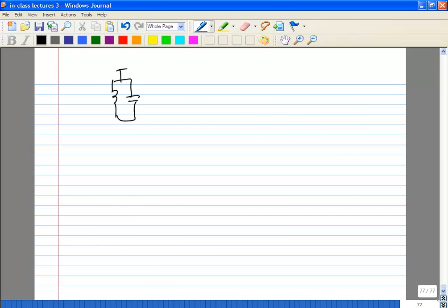So let's say it's like this, and you're going to do the feedback. The first problem you have to face when you do the feedback: what is the input impedance looking in here? Approximately 1 over Gm. We'll neglect the output impedance of the transistor. So it's typically very small. Typically it's a low impedance point, so you don't want to load the tank.